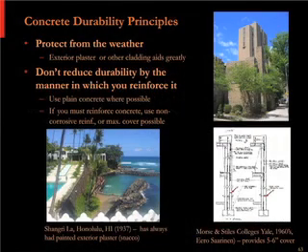And protecting concrete from the weather, they almost always covered it. So this example I showed, that's original stucco on the Curia in the Roman Forum. And on a lot of the residential buildings at Pompeii and Ercolano, you can still see the plaster facing on the brick-faced Roman concrete. And at the lower right, that's really the typical Roman construction.